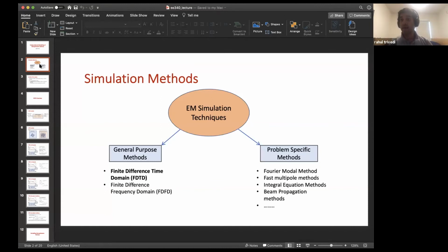And the antenna design community, which existed 30 years back, used integral equation methods a lot, right? Because their antennas can just be described by a shape, by an interface. So it's a perfect electrical conductor. It's a very good model for antennas, and you can describe it by just the outer shape of the antenna. And then you can use an integral equation method to simulate pretty large centimeter size antennas pretty fast, right?